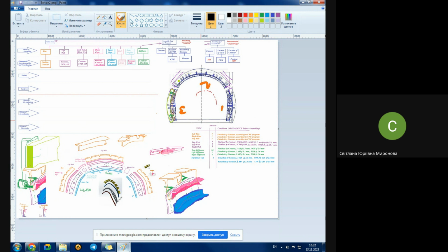It describes some important moments of jig design and jig coordination techniques, so that the designer may know what was decided by the previous engineers who selected the diagram of assembling, who selected bases and so on. Because in real life the jig is created after you have all the incoming information. Incoming information is the diagram of assembling, locating chart, and part supply conditions.